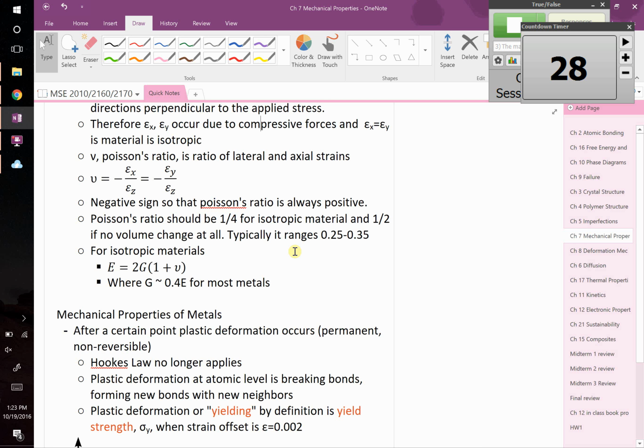Its density can increase. Cork is not a fully dense material. It has tons of pores in it, right? It naturally grows that way. So as you squish it, you're just compacting those. So it technically is getting wider. It's kind of a trick question, right? It's getting wider because its density can change. It's filling in those voids. If you had a cork somehow that didn't have those voids in it, it wouldn't be cork anymore, but it would now expand, right? Now rubber is the other extreme. As you apply something, it's so compliant, it's so easy for it to deform that it just expands very, very, the maximum of any known material, basically, 0.5, okay?